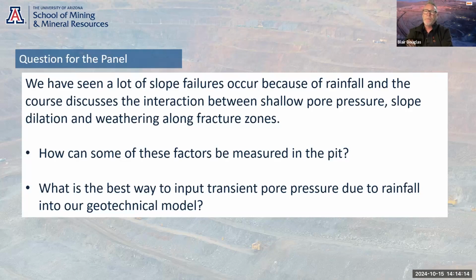So that first point about what can be measured, yes, we can put in piezometers and measure them through instruments, but I think there's also the need to make sure we understand the structural domains we're operating in, how these structures and their scale, where they could occur, and seek to look for things such as tension cracks which open up, and map them, understand them.